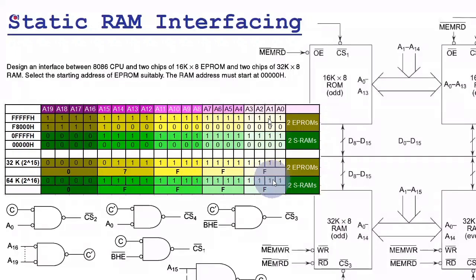So if you convert it to a hexadecimal number by grouping it into 4 numbers as you have seen here, you will get 0FFF, right? If you add this 0FFF to the initial address 0000 for the actual physical RAM, you will be getting the last address. So the last address happens here to be 0FFFFH. So this address range is fixed for your two set of RAMs, and the constraint that it must include the address 0000 as the beginning address is already satisfied.